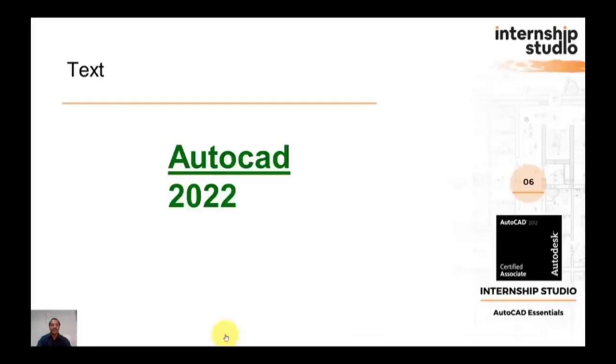This is our text on the screen. Now we have two lines of text. In these two lines, which is left, right, middle, center of the justification? So if you see here, what is left? The top line, bottom left side is the left point. Similarly, top line, bottom center is the center point. Top line, bottom right side is the right point. And the first line, center point, that's called the middle point.